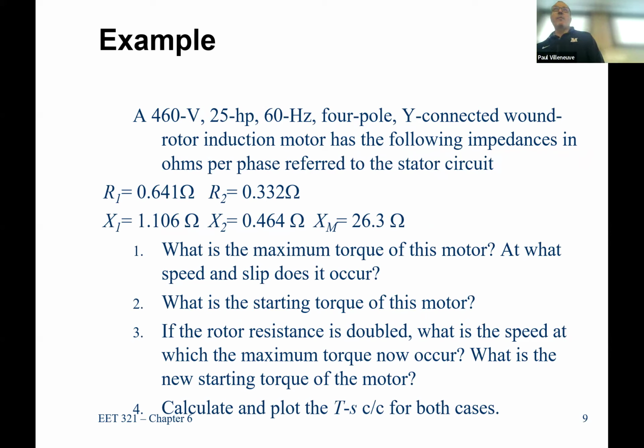Very first thing, and hopefully this has been clear already, that's irrelevant. 25 horsepower means nothing to me. Why does it mean nothing to me? Because that's just a rating on the motor. It doesn't tell me anything about how this particular machine operates.